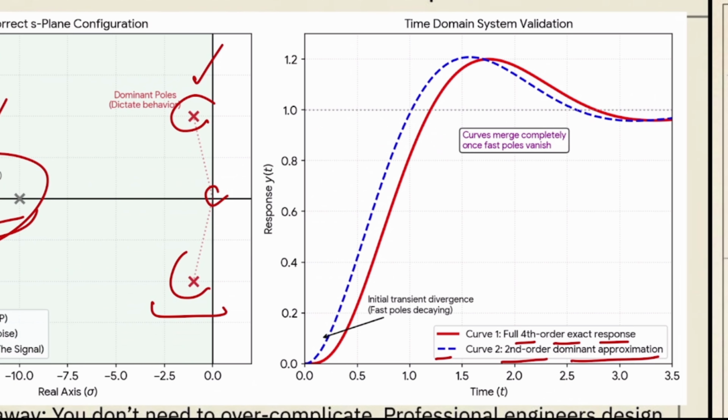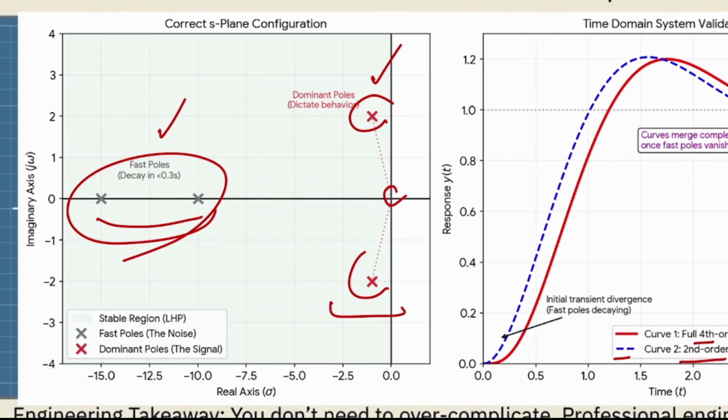But why are they identical? Because as you can see over here, the poles on the left side, something that we call the fast response poles, have way more distance in comparison to the normal poles that we call the dominant part. So at this point, we can say somehow their impact on the system itself is going to be fast, and also is going to vanish so fast.